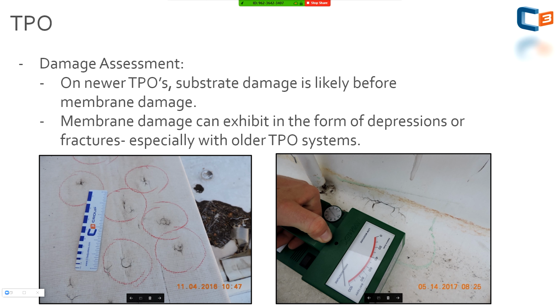The one on the right side, so this is a good example of a TPO membrane that's a great product. It's very stable, as we just went over. But it was over a substrate type that played a huge factor into the replacement of this roof. So in this case, we only had probably 8 of these impacts, and they were huge. And notice it's at a transition. It's out where there was a little void there.